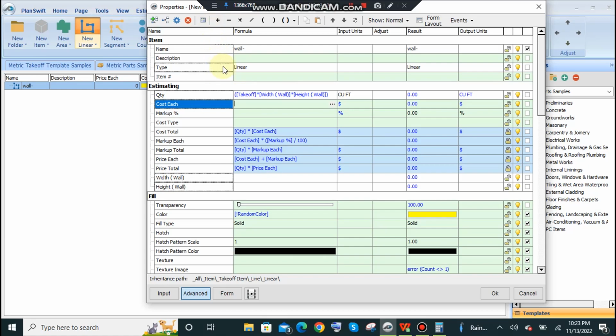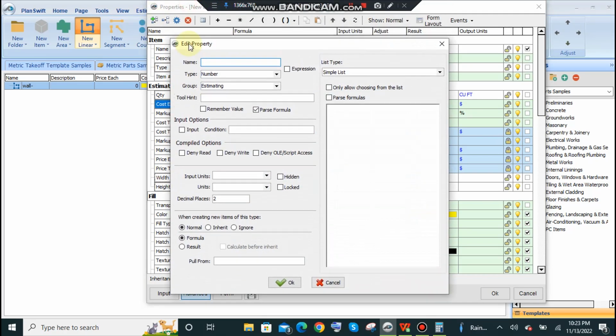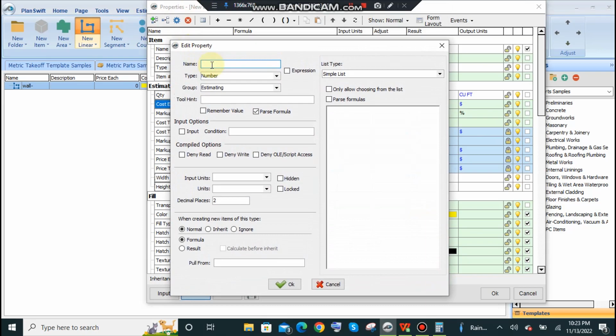Now this is not the actual volume of a wall, because from this total volume we need to subtract the total area of openings. So openings, suppose we have doors, three types of doors, and windows. So we have to add length of window 1, suppose.